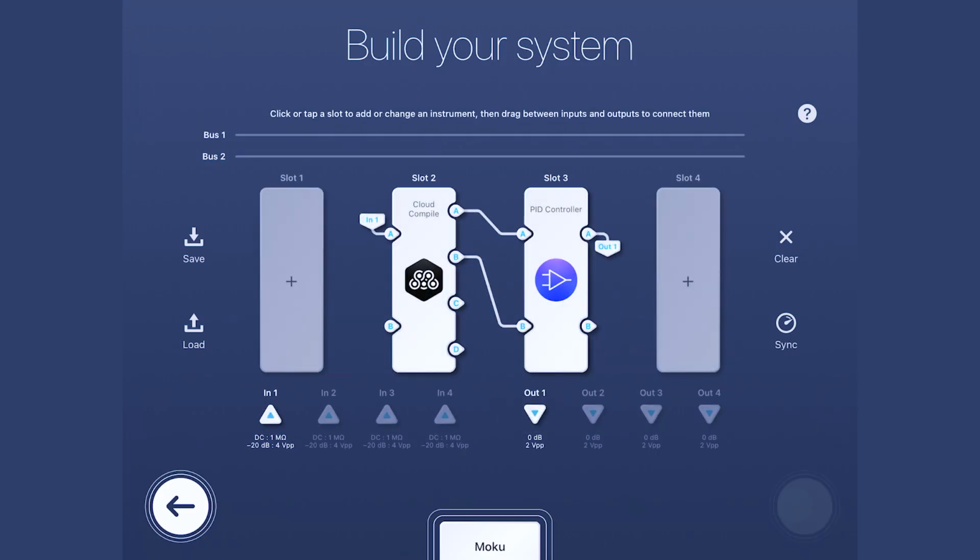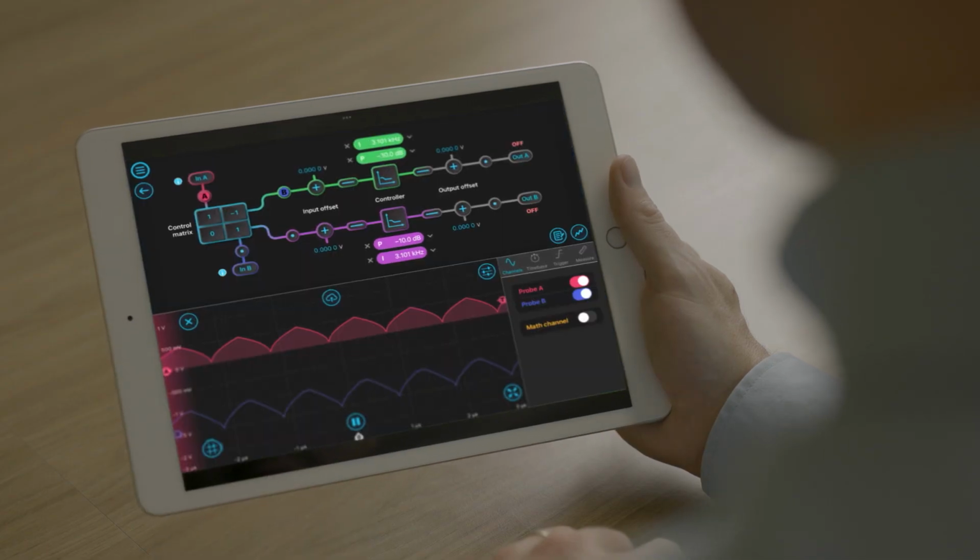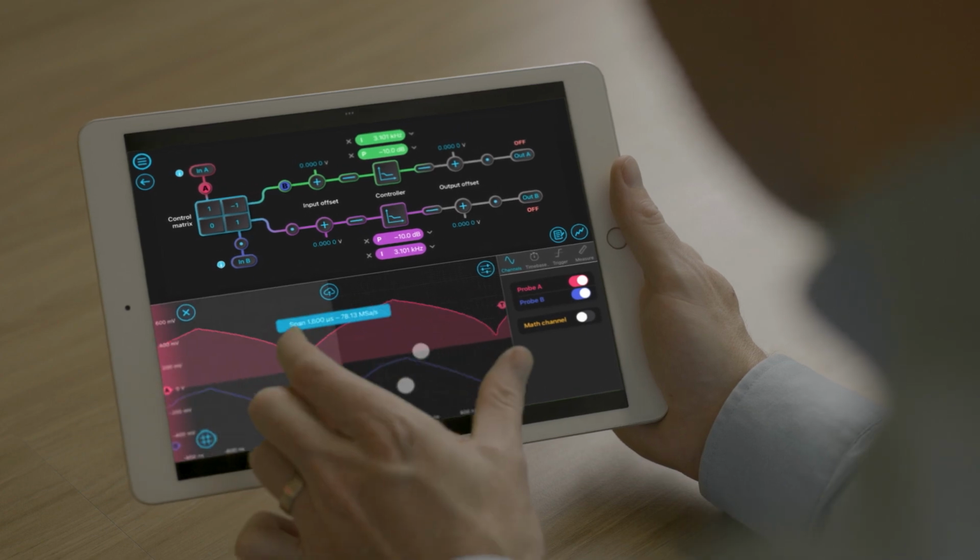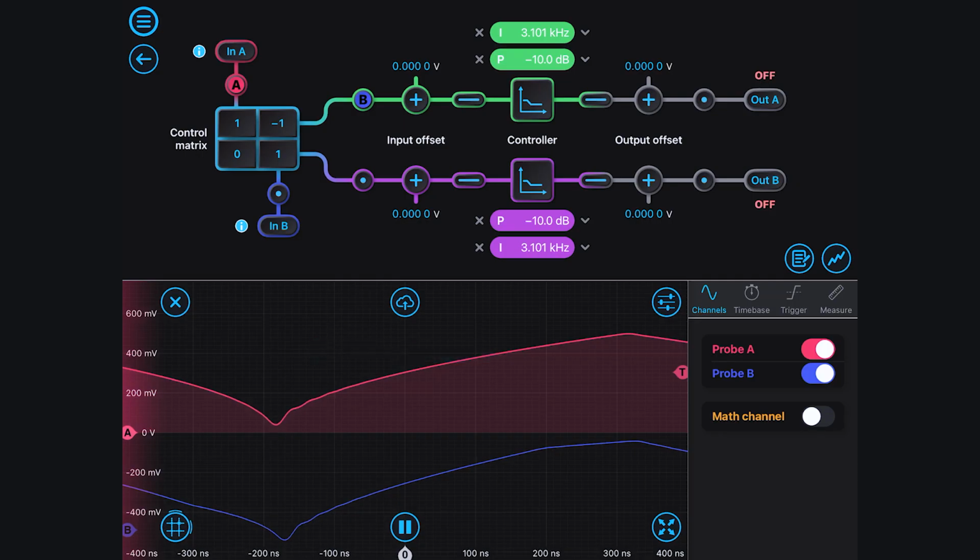For example, you can quickly deploy custom algorithms that pre-process your error signal, maybe linearizing it or filtering it, before the signal enters your PID controller. A simple example here might be when detecting power but controlling voltage. You can take the square root of the input signal before the controller, greatly increasing the effective dynamic range of the system.